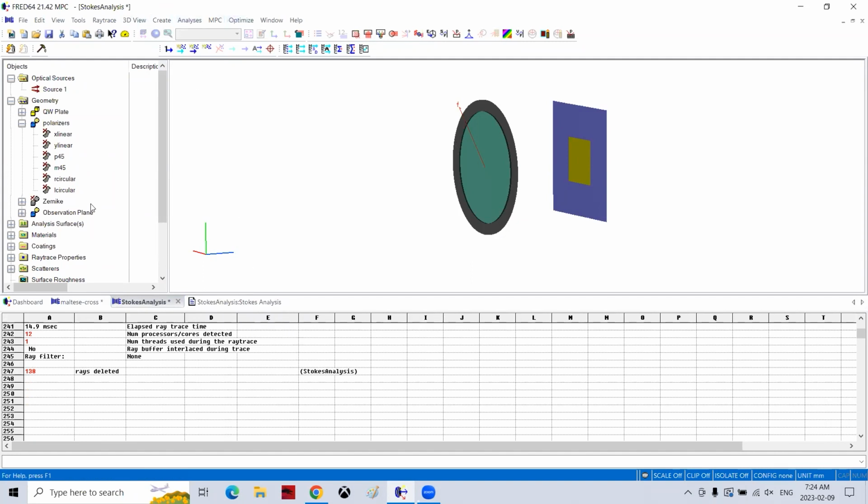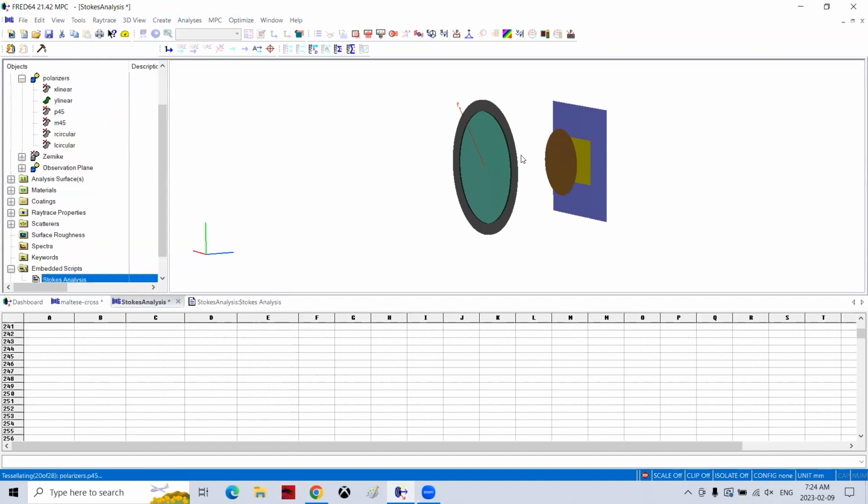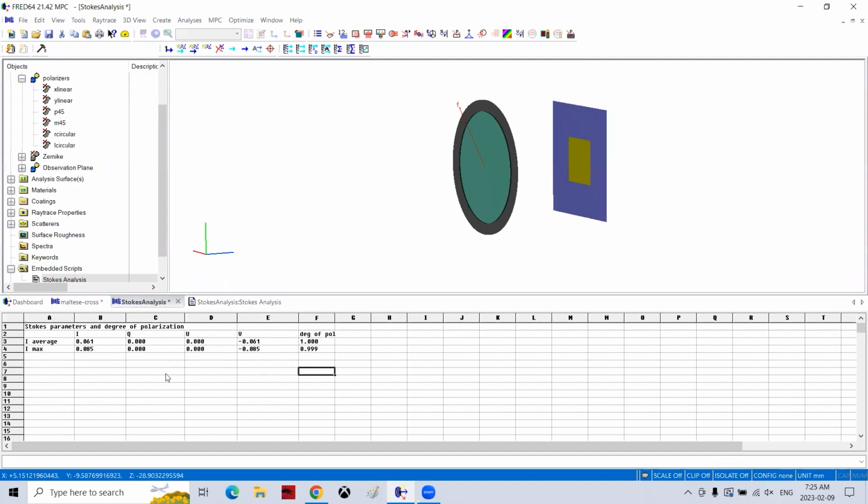Okay. So right click, run. You can see here the dummy plane switching on and off as we cycle through the list. And we can see here quite simply the results. Hopefully you can see that on your side of the webinar. What we've done here is actually calculated it in two different ways. We're using the average irradiance values and the maximum irradiance value, just to see if they vary a little bit.